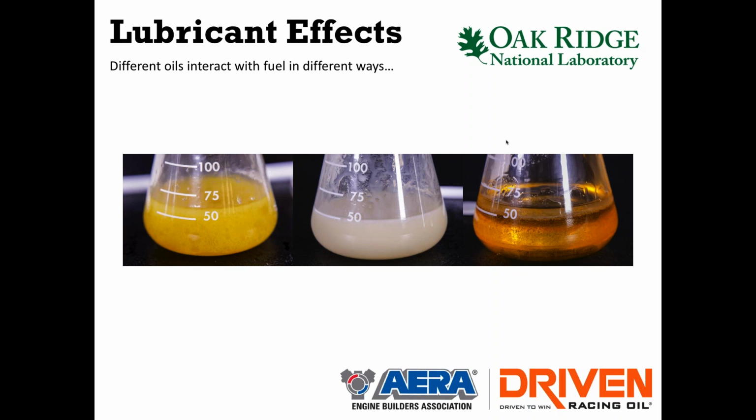The image in the middle is very milky white, where you have a hard emulsion, where the fuel and the oil are completely emulsified together. And then the far right, where you have a complete separation between the oil and the fuel, where the fuel and the oil don't want to mix. Obviously the far right scenario allows the fuel to evaporate due to piston temperature and engine temperature, and make its way out of the oil and out of the engine, so you don't have that mixing.